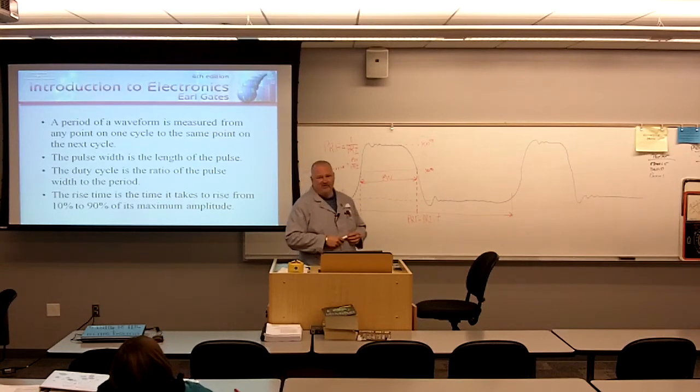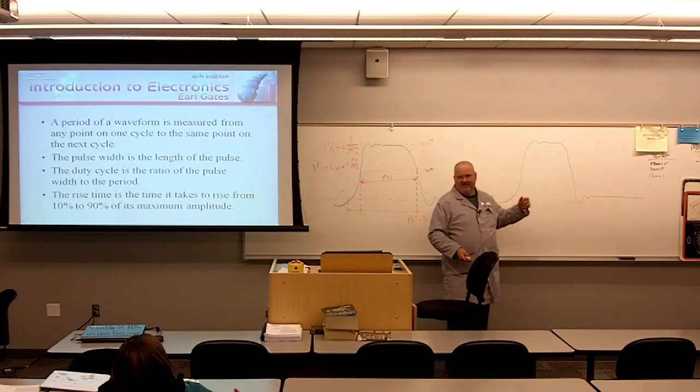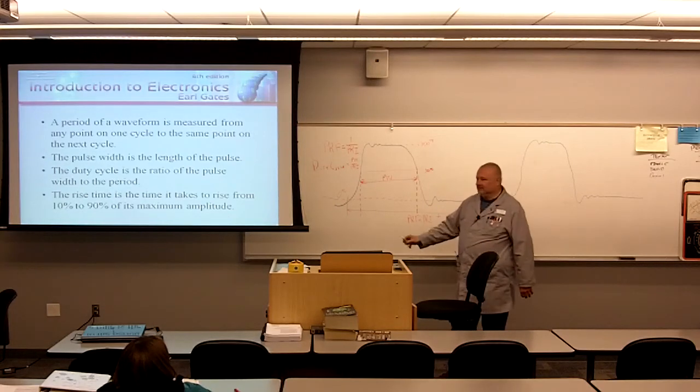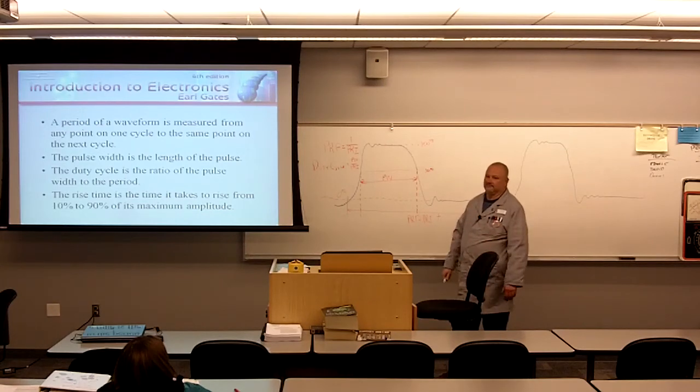So if this was a real radar, this would be a very short-range radar. It'd be a very powerful short-range radar. This might be for something like navigating in a river or tight-in area. But this doesn't give enough time for you to spit the pulse out and then listen to the return, because it's got to travel at the speed of light to the target and then all the way back. So this wouldn't be a radar designed to look at something 400 miles away. This would not be a radar that's going to detect a missile launch or something like that. This is something close-in, a navigation radar. So by looking at this stuff, you could tell what it's used for. Make sense?